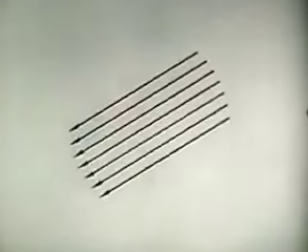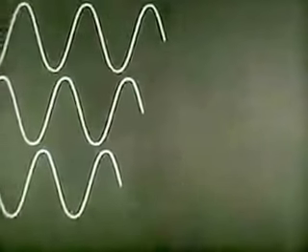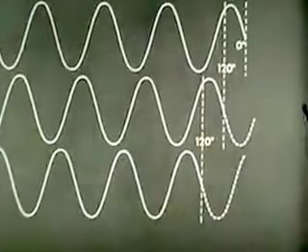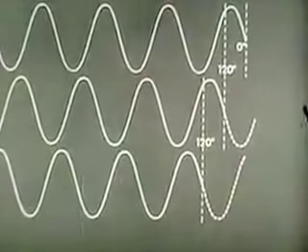It is necessary to find a way to rotate the field electrically. We saw earlier how 3 voltages 120 degrees out of phase were generated. This voltage can be used to rotate the field electrically.